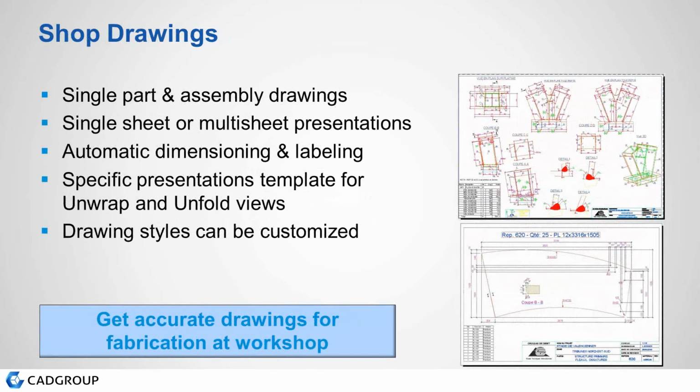Shop drawings, as I mentioned, you can do single part drawings, assembly drawings, automatic dimensioning and labeling, and a specific presentation template for unwrap and unfold views. So the program also has plate work that you can do, although I prefer Inventor for that kind of work if you've got Inventor, but if you don't have Inventor, you can do plate work within the program. So if you want to do unwrap or unfold views, there are specific presentation templates for that. All the drawing styles are customizable. You can decide what type of dimension styles and text and all that stuff that you need.